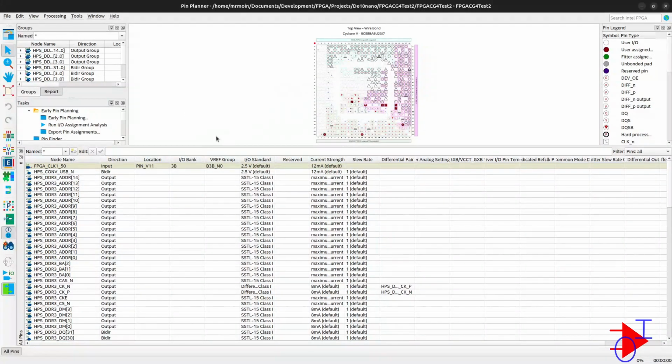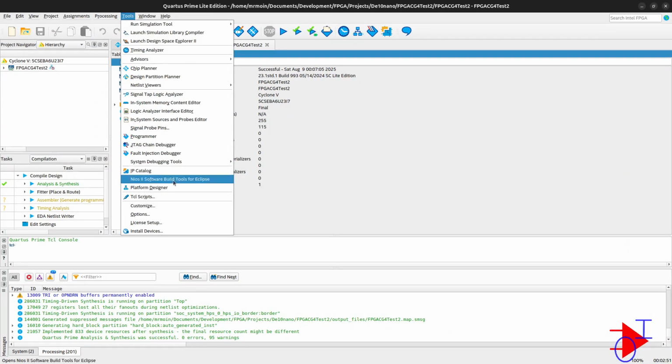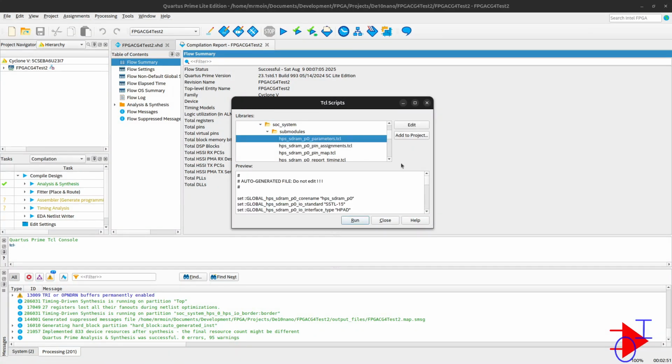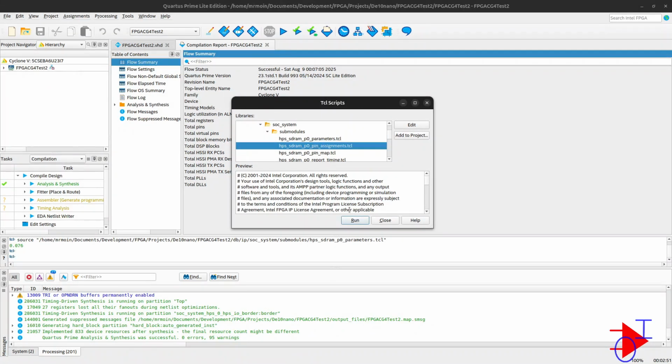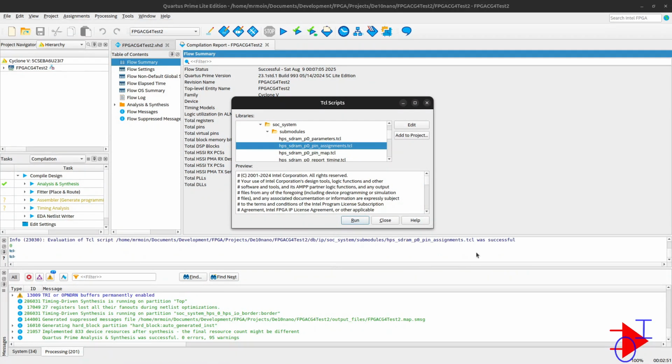Okay. Now that we have removed Ethernet, I believe we have to rerun the TCL scripts. And then once we run the TCL scripts, we can run our full compilation. So let's run this one more time. Assignments complete. Seems like it's going okay. Looks like it. Come on, come on. Okay, successful.